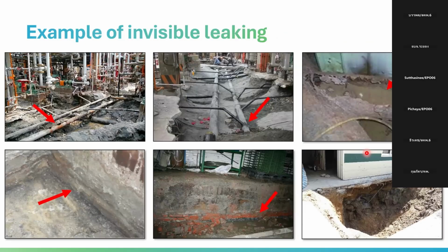So you can see that this is a big hole here in the underground pipe, this black one. And when you open the surface and figure out what happened here, sometimes between the buildings and their basements, there are some leaking points, and the old brick-built manhole should be located here. Some leaking points are at the bottom of the buildings.